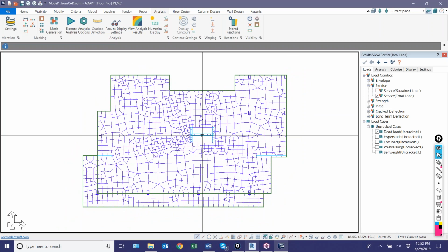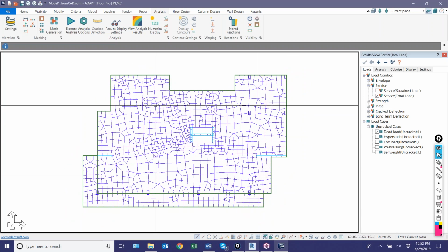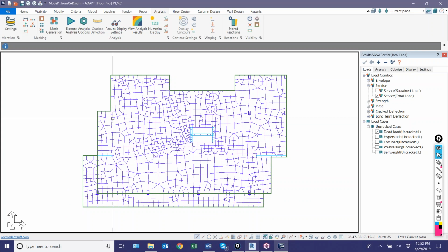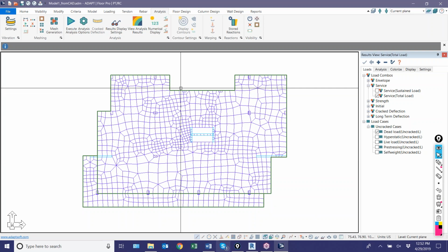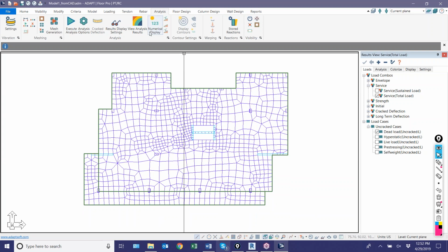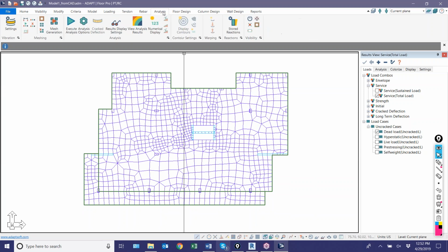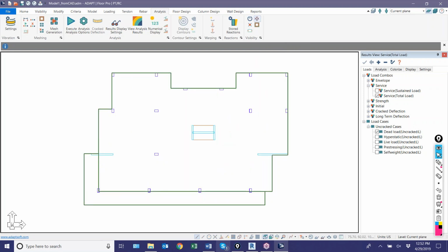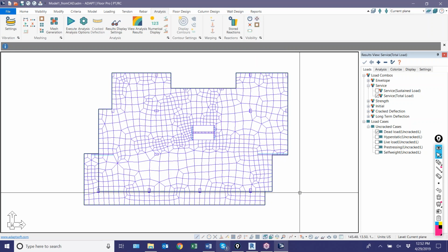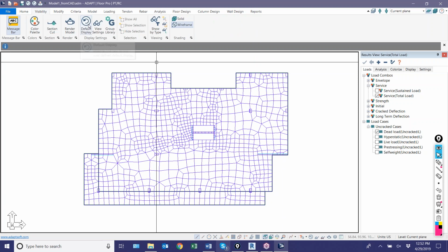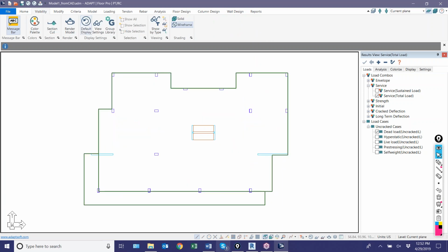Okay, I'm going to switch over to a top view, and you'll notice we don't want to retain the view of the elements on screen. That can make it a little more difficult to see things in terms of results. So I'll go to analysis, and under analysis there's this option for visibility where I can turn the elements off. If they're left on and you just want to use the default display, I don't have shells set to my default, so I can always use that as well.